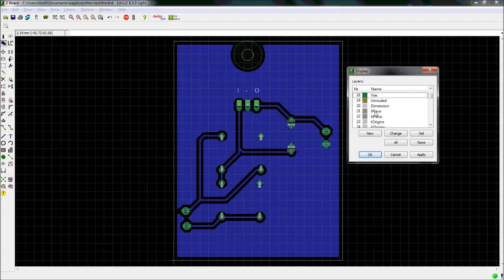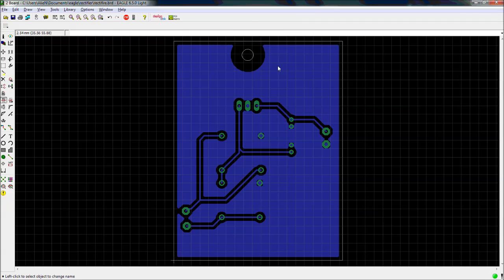You can choose vias or not, because we didn't use vias, and dimensions. Just hit apply. Okay. Now you can see this. This is the copper sheet. This is vias, and these are routing wires, or you can say connecting wires. Fine. Okay. Now you can also send Gerber files to the manufacturer to manufacture the PCB. But if you send a file and tell them to manufacture just a single PCB, it will cost you very high. So we use a general, very popular and cheap method.